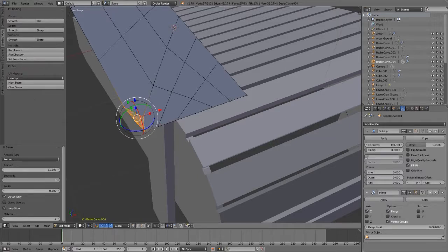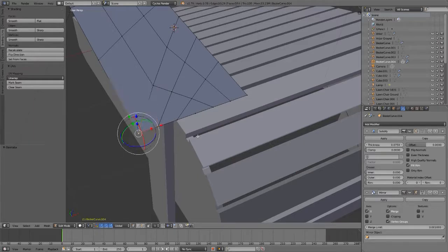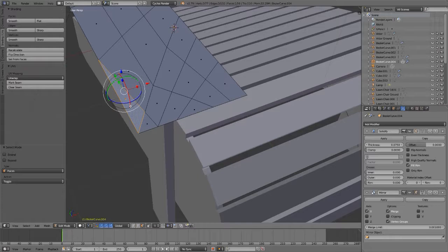So I know that beveling is a destructive feature if you're not using an add-on, but the good news is we can actually change a couple of things after. I've totally screwed this up. Okay. Or we can select a nearby vertex, shift right click, select another nearby vertex, press J on the keyboard, Control Tab F, go into face select mode, take the resulting triangle, shift right click, select the next resulting triangle, F, join them as one face. Hallelujah. Control Tab V, go into vertex mode. Now we no longer have the problem we had.